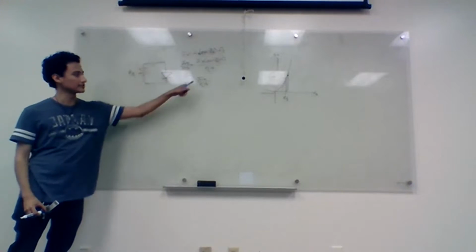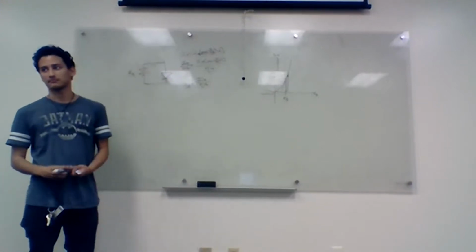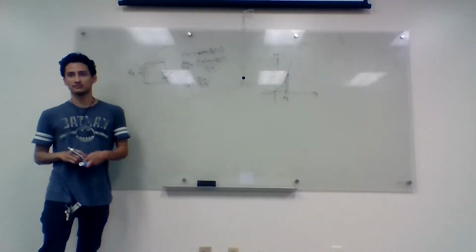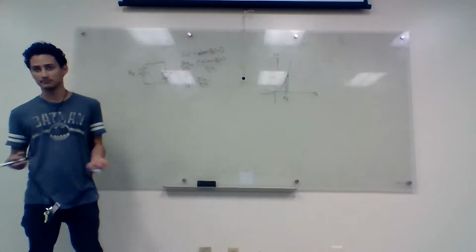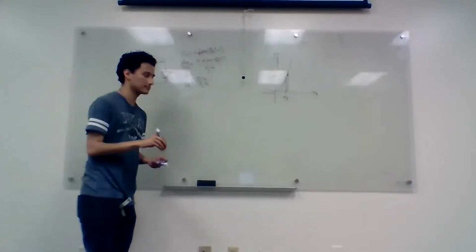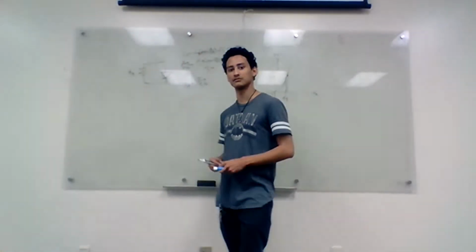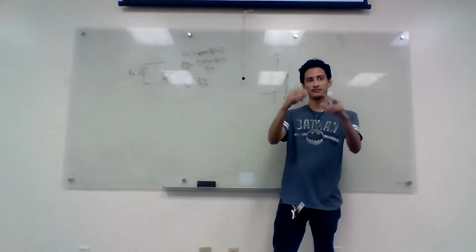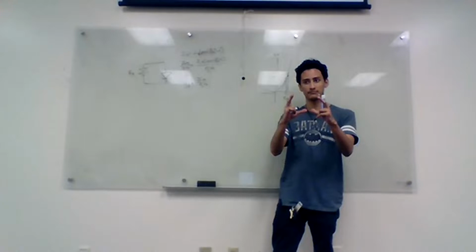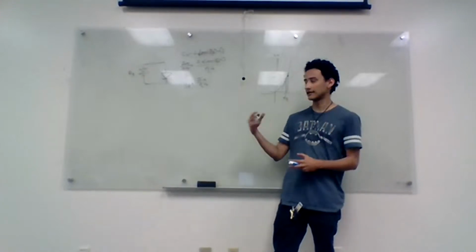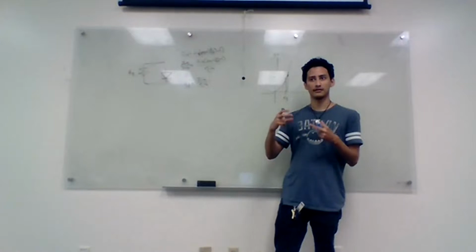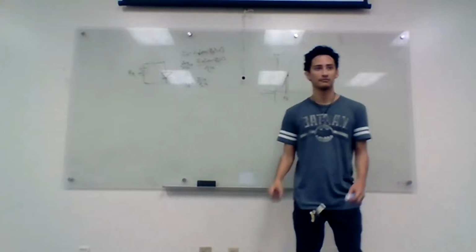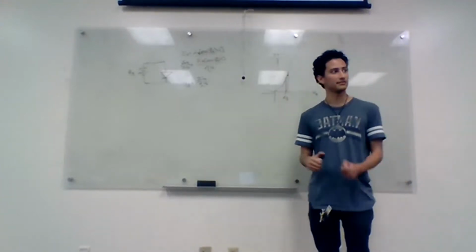The ID value that's going through here, that's what you put up. That's how it works for all of the small signal models. Those come from their derivatives in the materials. What you're doing is taking the operating value, the actual value that it's biased at, the actual current and the actual voltage, and taking the derivative and then using those values to get G sub D, C sub D, all that.